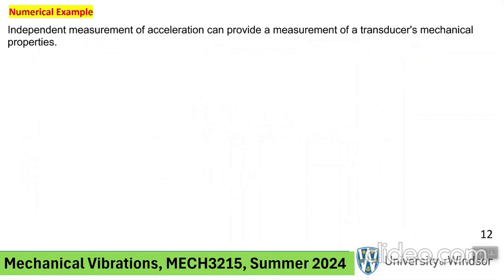In order to get your omega n and zeta, you need another independent measurement of the acceleration. So some other gadget, either another accelerometer that you knew the data of, whatever, you used it to come up with the quote-unquote correct acceleration value.